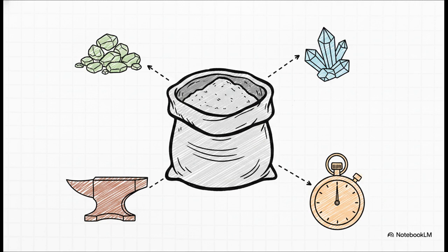But you have to be careful. Excess lime actually makes the cement unsound. Then we have silica, sitting at 17 to 25%, which combines with that lime to form highly durable calcium silicates. Alumina is what helps with quick setting, and iron oxide gives cement its distinct hardness and that familiar gray color.